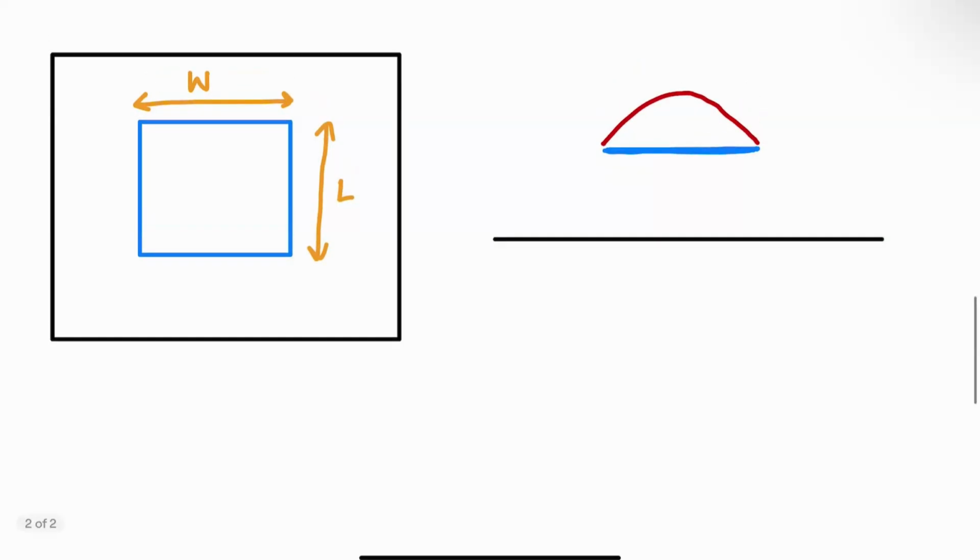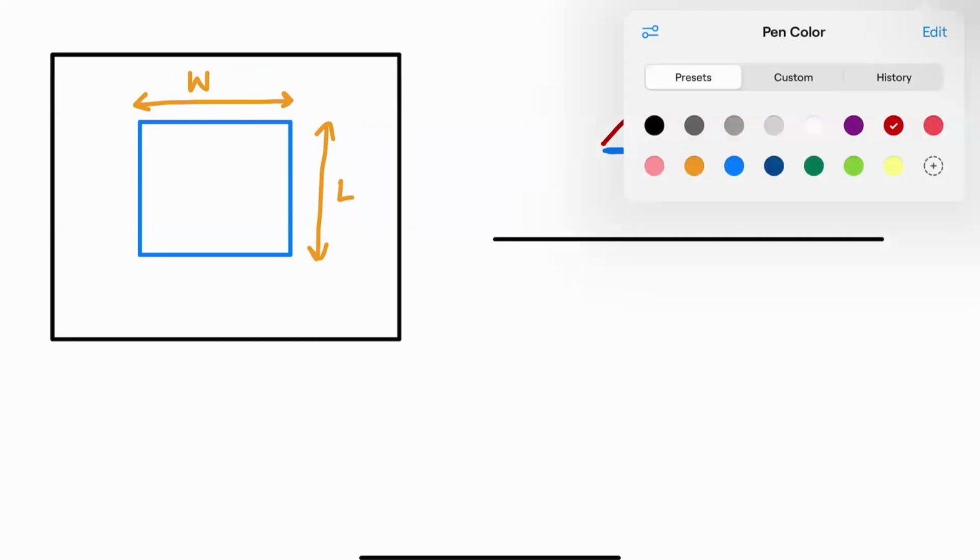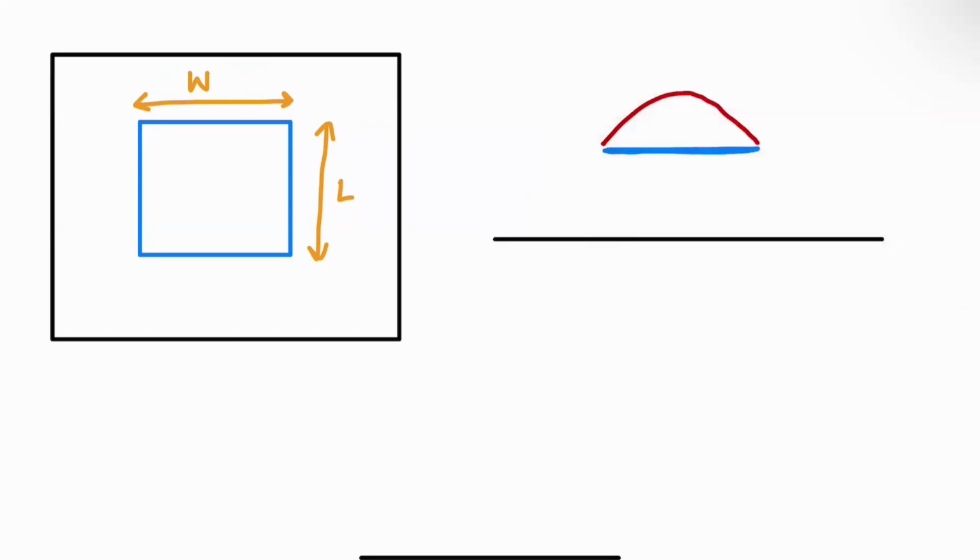Okay, and if you think of this as a transmission line, since the current is zero at the ends and maximum in the middle, the voltage should be the other way around. So the voltage would be like that. Let's see, you have maximum voltage at the ends where you have an open circuit and you have zero voltage in the middle.